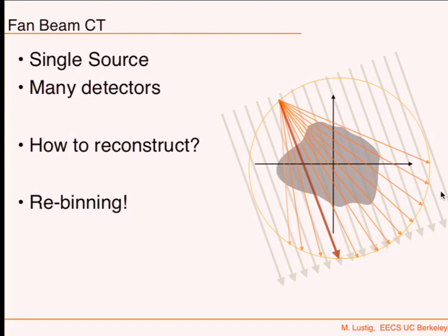In that packet structure, you are able to do some routing and error detection, and implement what's called the APRS protocol, part of the AX.25 protocol, which will allow you to communicate with other stations that people put up in Berkeley and other places. You'll be able to send packets that contain information, to send yourself a text message, to report your position, to send an email, or to text message between each other.